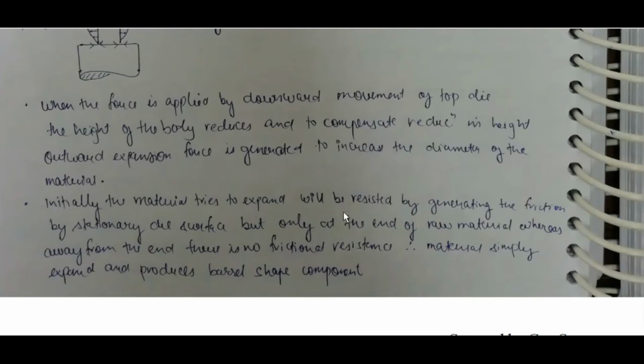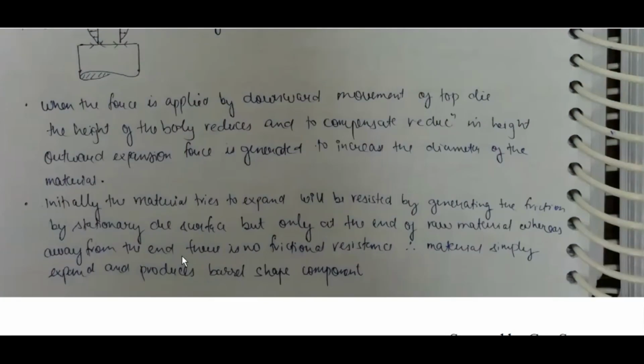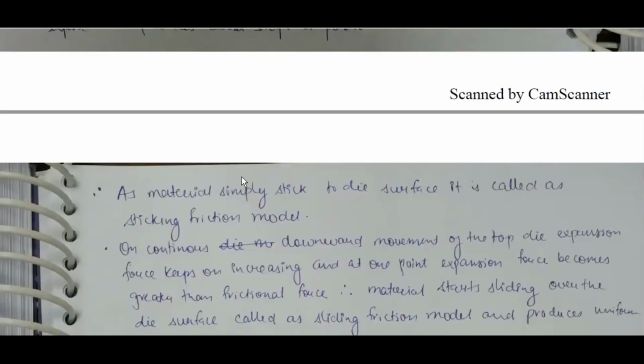Gutter, parting line, cavity, thin flash land. In closed die forging operation, an extremely thin flash land is provided between the gutter and the main cavity. Therefore, during actual forging operation, a lot of pressure is required for moving the material through the thin flash land, and therefore slowly the pressure in the cavity starts increasing, which allows the material to fill the entire complex intricate shape of the cavity.